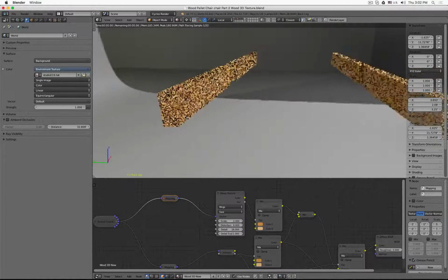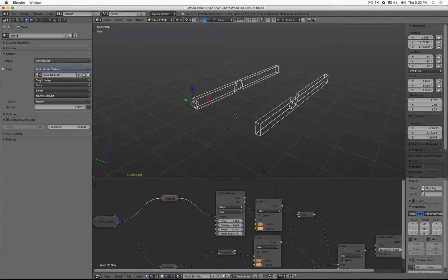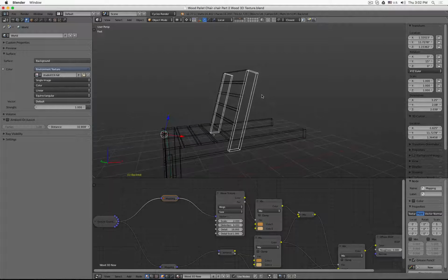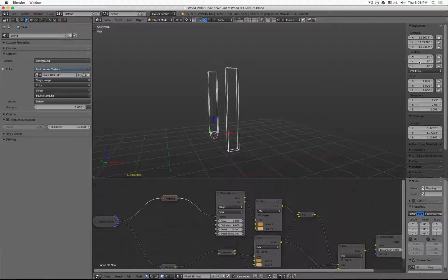And there you can see now the correct orientation. Perfect. Alt H to show everything again. Shift H, Shift S, cursor to selected. Now this one is rotated 15, so let's keep this in mind. We first set this to 0, so it's easier.